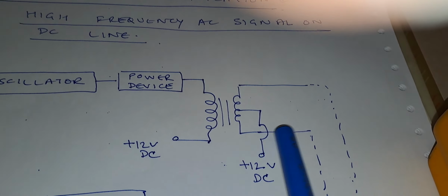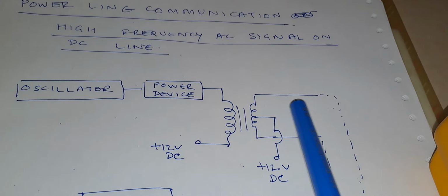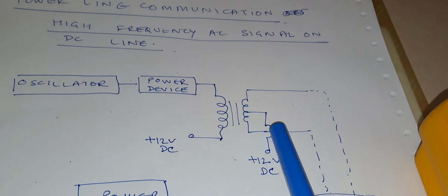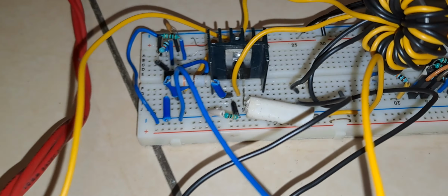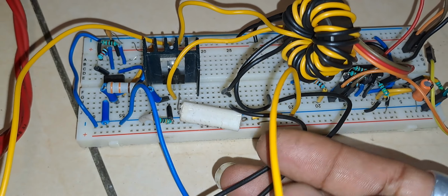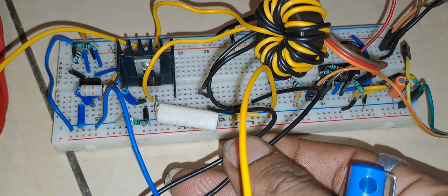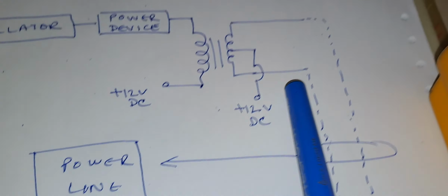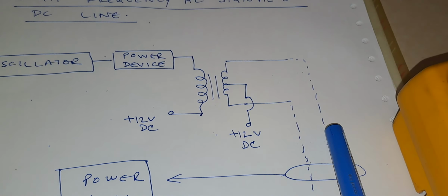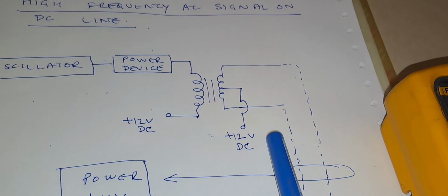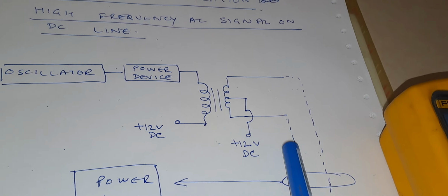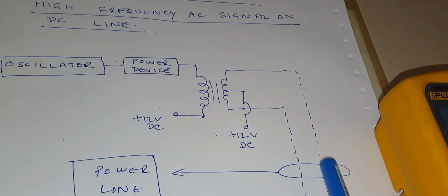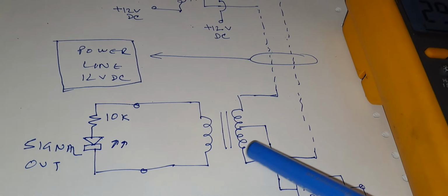As you can see, the other two wires are forming the communication loop. These two black wires are the power line communication. Basically power will flow in these two lines as well as communication data. Whatever signal I am giving from here will be transferred through these two lines and will be received on this transformer.